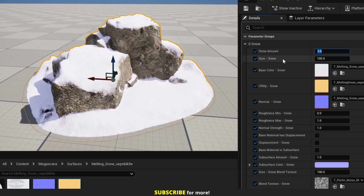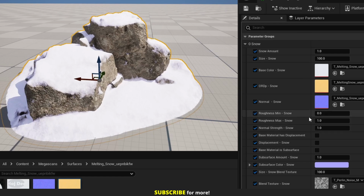Size controls the size of the snow textures. It's in world space units, that's why the default value is 100, which is 1 meter. Roughness and normal parameters are self-explanatory. By default, it's assumed that the base mesh and the snow don't have displacement. If the base mesh has displacement, we should enable this option.